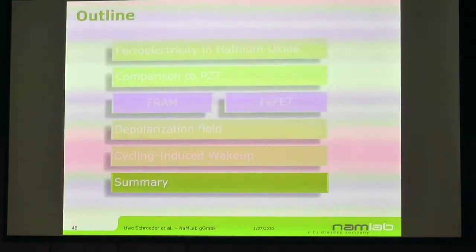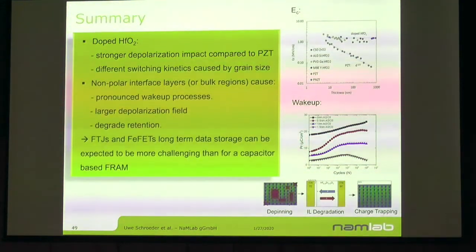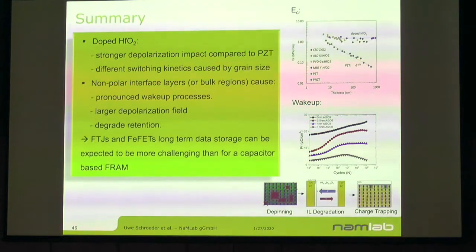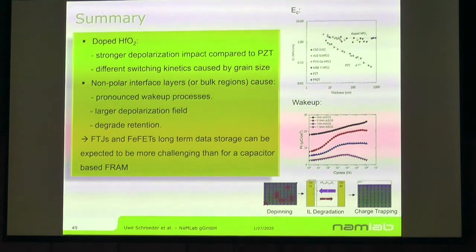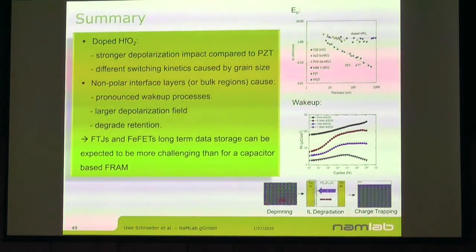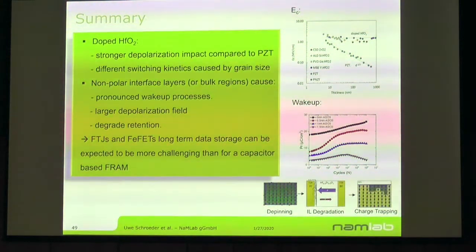So with this, I'd like to come to the summary, and I hope I could give you a nice overview of how hafnium oxide works and how it compares to the PZT case. In hafnium oxide, since we have really thin films, we have a much stronger effect of nonpolar phase portions in the layer, and with this a much stronger depolarization field compared to the PZT case, and these cause the wake-up effects.